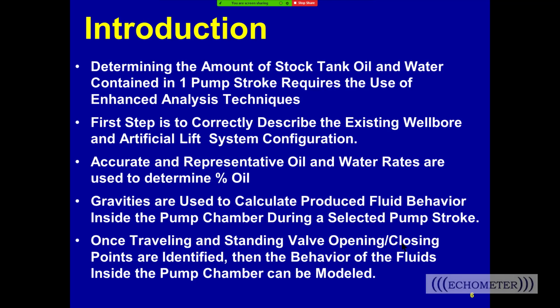If you turn to another stroke and it has a different opening of the traveling valve, then it's going to have a different adjusted pump displacement. Now, we use the deviation survey, we use the wellbore information, and we use the artificial lift, plunger size, plunger length, the rod string length, the rod string sizes, all those different parameters.